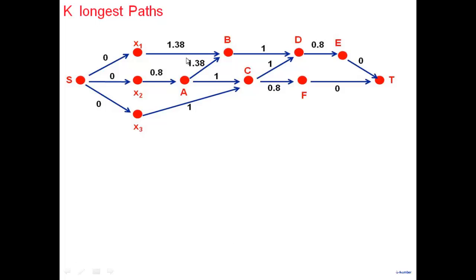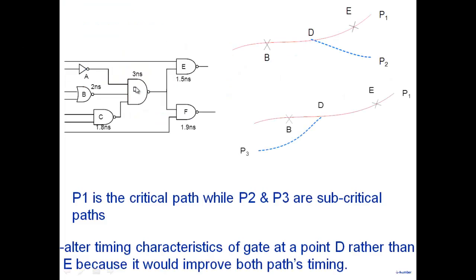But there's a problem. If you go back and look at, for example, when I go from A to D, I have a delay of, let's say, inverter A, and a delay of this particular D. But when I connect A to D, there is a wire here. And the wire has capacitance in it. And the wire delays have become very important. Now that information I don't have.